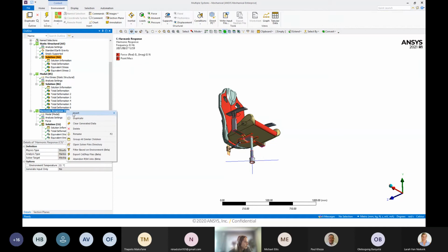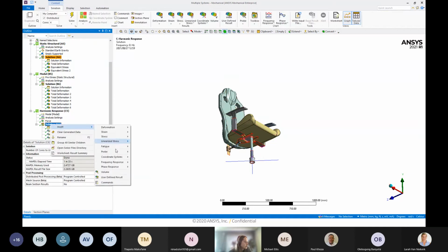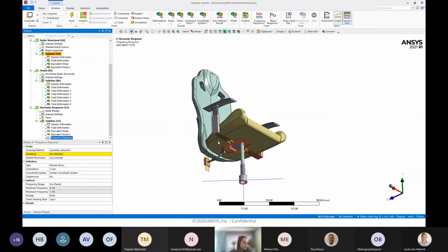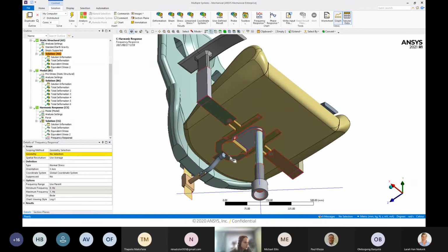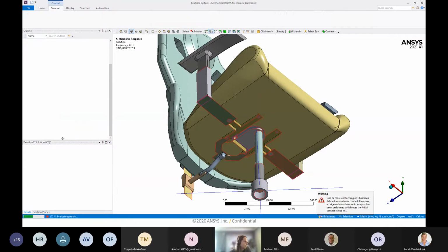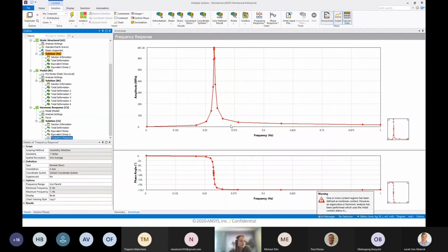Then you can also request specific frequency response plots if you need that. So I'm going to plot a stress response plot of a vertex. I think I'll select this one, which was the worst. And then this will also give you the Bode plots of the response of the system. So that is quite cool. In this case, you can see the amplitude and the phase angle to see what the lag is of the response behind the applied load. So that is quite nice.